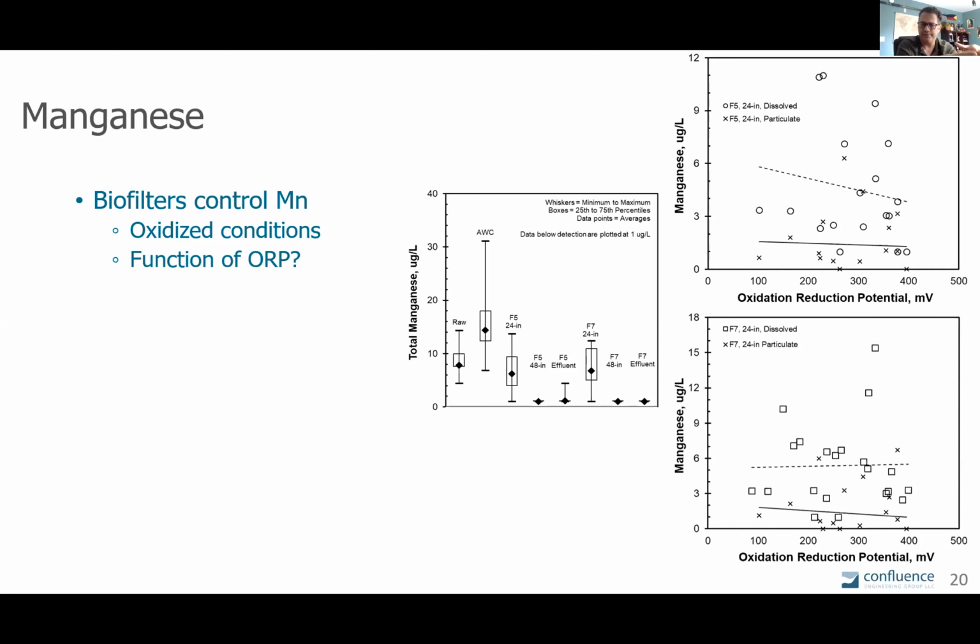And then once you get into the filters, you have a very high surface area because you don't just have 4 walls and a basin anymore. You have the filter media everywhere, and the iron and manganese is being oxidized possibly onto the filter media. So we want to pay attention to that, and if there's any changes in ORP, does that iron and manganese come off, or is it a particulate that's being removed and being pushed into backwash? That's something that needs to be studied a little bit more, and we'll talk about that more later.